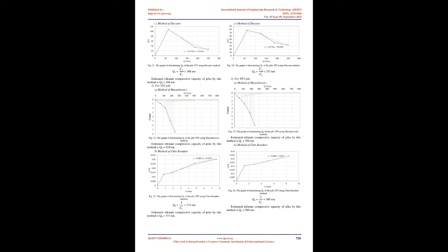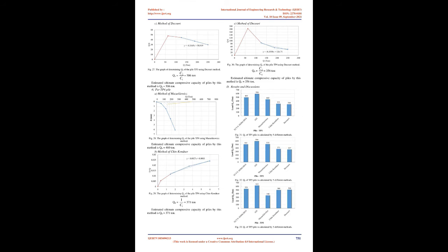Then, the formulas for determining the ultimate bearing capacity of piles in Vietnamese standards are applied to calculate the pile bearing capacity. The ultimate bearing capacity of piles according to the standard uses the symbol RCU. The parameters in this formula strictly comply with the provisions of the standard. Its value depends on the geometrical characteristics of the pile, the physical and mechanical parameters of the soil obtained from laboratory experiments such as liquidity index, physical state, soil type, and tip depth.